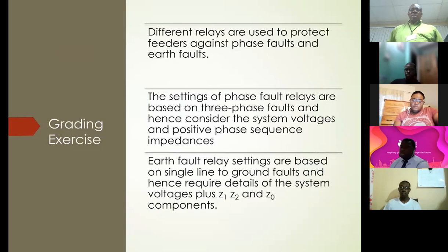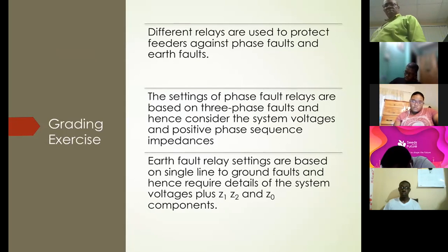In terms of the relays, you're not going to use the same relay to protect against phase fault as against earth fault, because of course the settings are going to be different. For your phase faults, you're going to be using the 3-phase fault current.